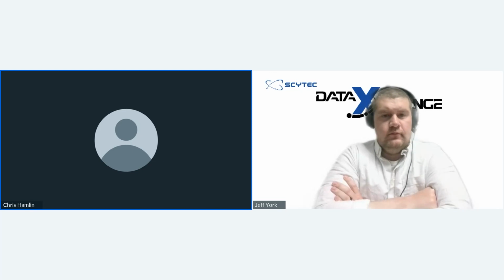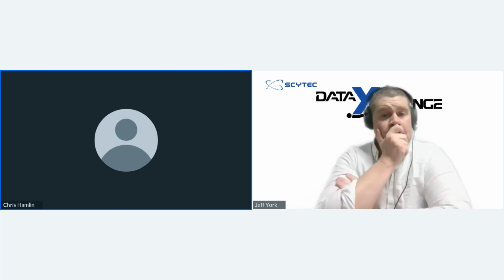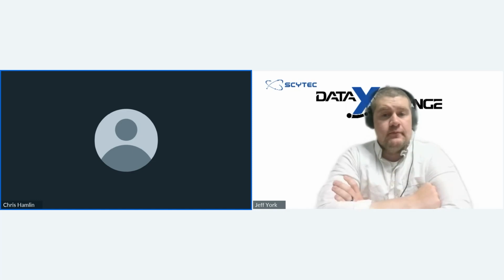One of the big popular ones that's popping up is people want to record the feed rate override and display that in the RTV view. So we can actually get the numerical value coming back from the machine. If it's at 100% and it's just running normal, we can record that 100 into the on-screen RTV view and display that. If someone's turned that feed rate override down and say they're running it at 60%, 80%, you can display those values live, again with very little latency, on the shop floor.